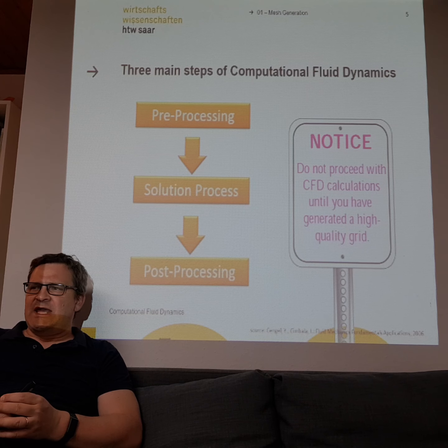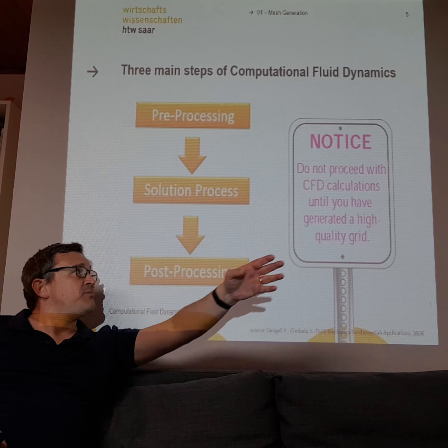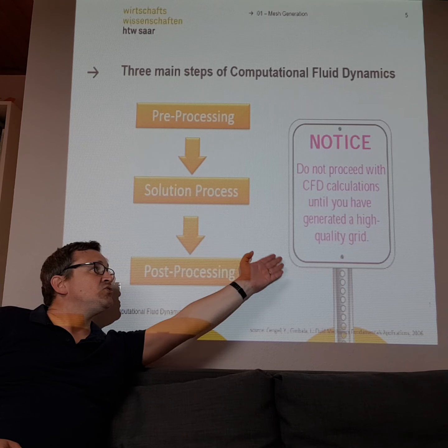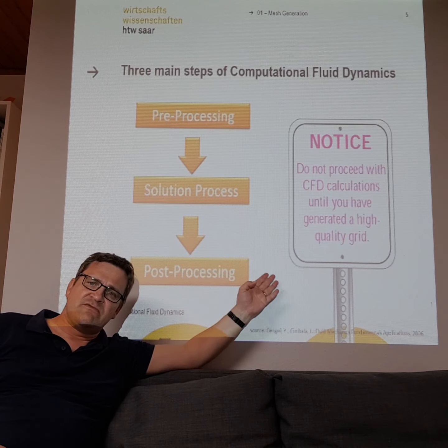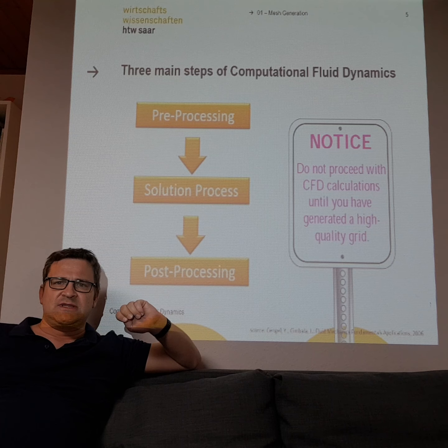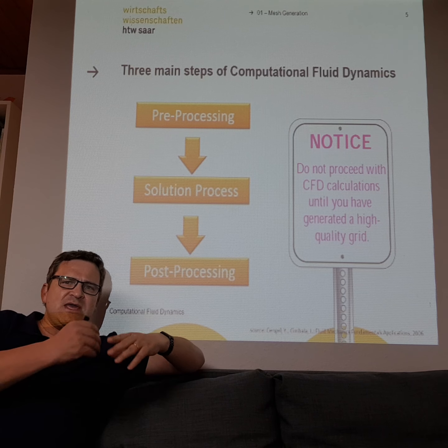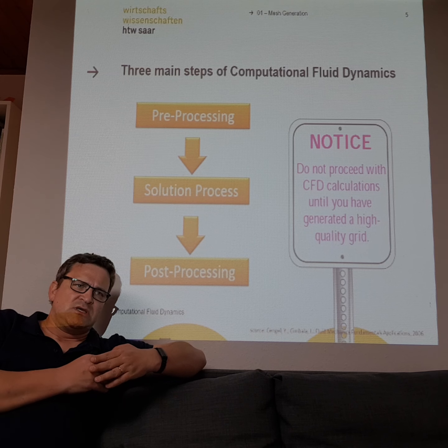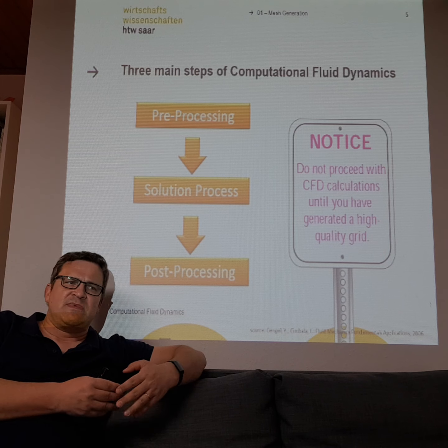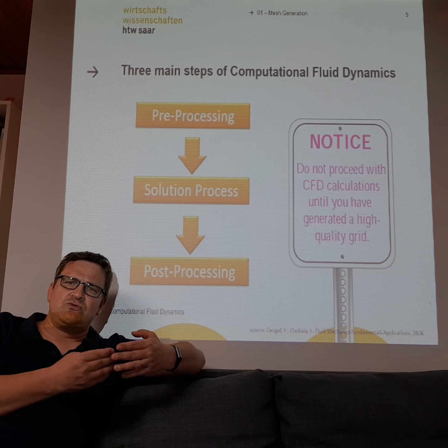Okay. And one thing is really important here. Do not proceed with CFD calculations unless you have a high quality mesh. That is really important. You can make bad meshes really easily and fast, but then your result will be wrong.